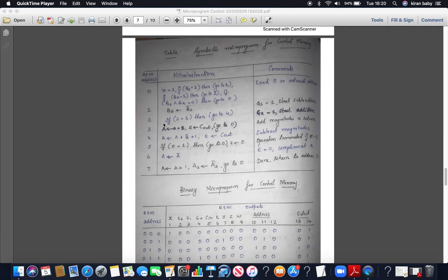If it is an addition, then you are going to compare the S values, that is the sign bits. If the sign bit XOR value is equal to 1, which means both of them have different values, then it could be a positive sign or a negative sign for those registers.